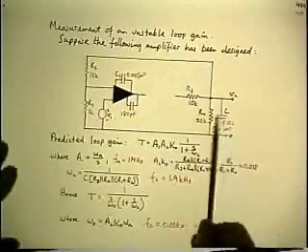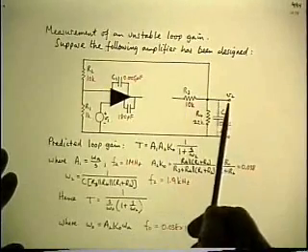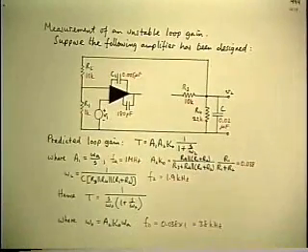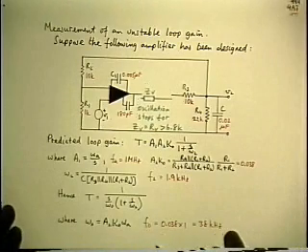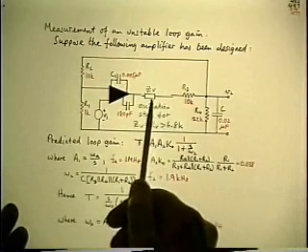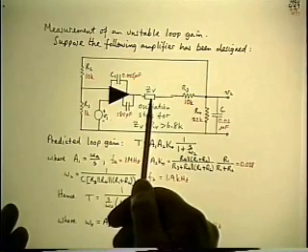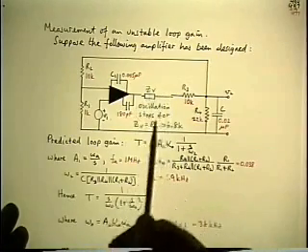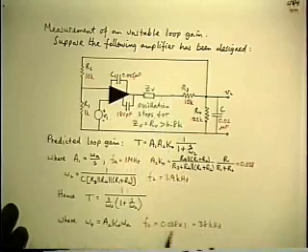So here's the circuit we built, and it's unstable when it's closed. So now, in order to stabilize it, you insert an extra impedance. Not just anywhere, but you insert it at the place where you are going to do signal injection to make the measurement. Because that is the one unique, only place where you can put an extra impedance in and not change the measurement.